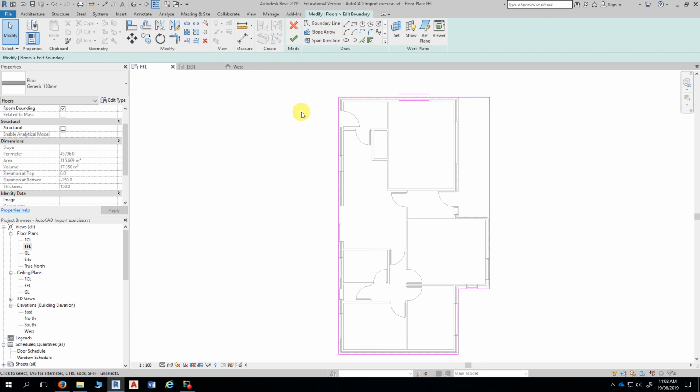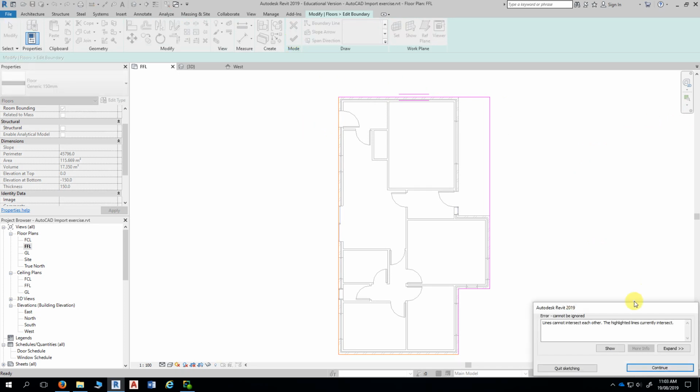So I'm trying to sort of here. Let's try that again. Lines. Maybe I'll do this one. You might not have green clicked after you did all those lines. Yeah. So I've actually managed to put a sketch line along here, and it says highlighted lines overlap. Lines may not form a closed loop. I'm doing this deliberately. So here as well. And when you go to finish, you'll get this error here.